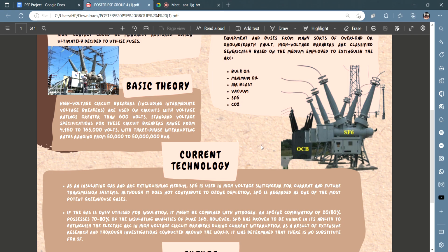During a fault state, the arc is dragged out horizontally and transmitted to a series of arcing contacts as the current carrying contacts split. At the same time, the blowout coil creates a magnetic field that draws the arc upward into the arc tubes.